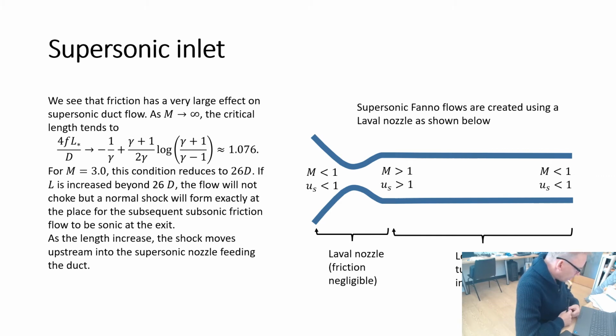So if the pipe is very short, then the exit flow is going to be supersonic, and we have this simple case C scenario that we've seen for duct flows. But if the pipe is longer, which is typical, then we would end up with a shock formation at a specific point along that pipe, in order that the exit condition is matched.